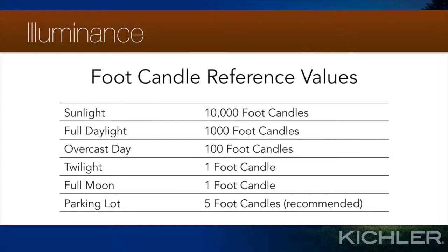For most landscape lighting installations, you are not aiming to create a parking lot effect. 1.5 foot candles of illuminance will subtly but visibly illuminate the edges of an object in the landscape.